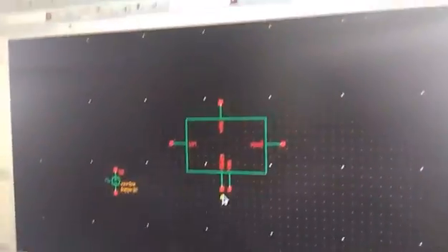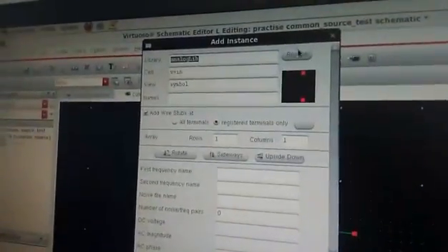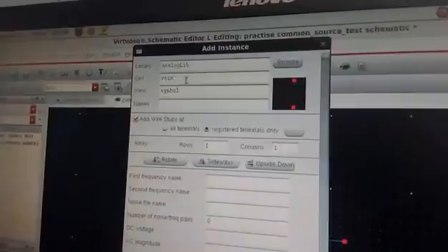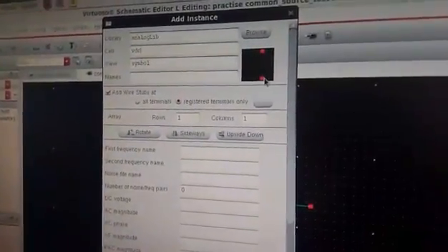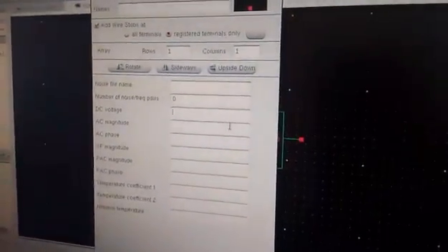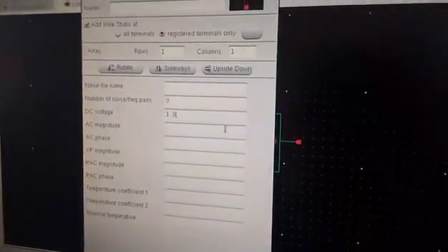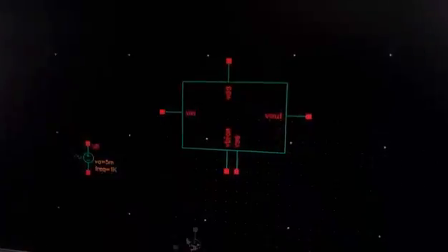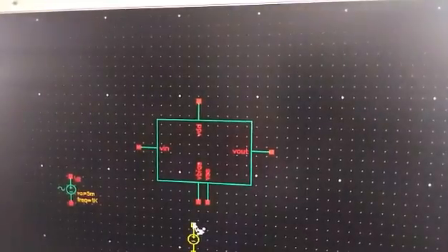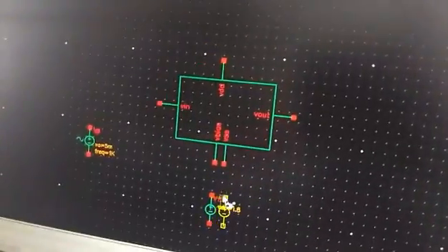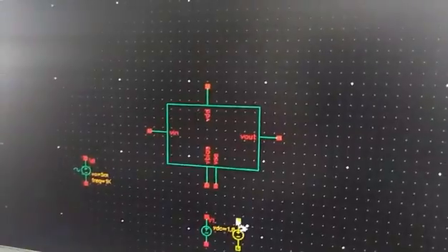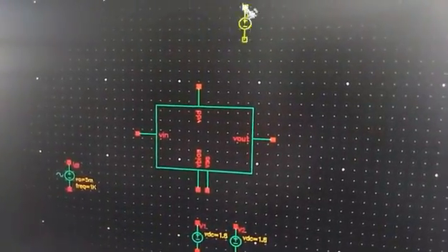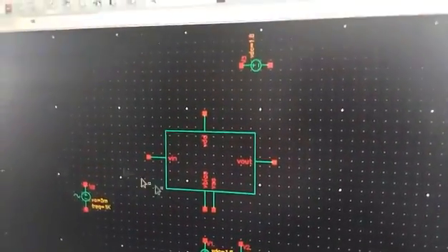Now it's time for our VDC. We need two VDC that produce plus 1.8 volts and one VDC that generates minus 1.8, which will be given to the V bias. Why are we giving minus 1.8? Well, the output we will be getting is an inverted amplified waveform of the input. So that's why we are placing our next VDC. There we go. The last VDC for VDD.